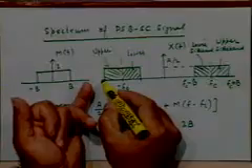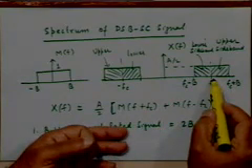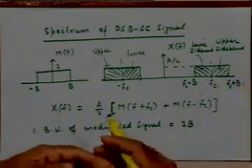No, what we are saying is, certainly we are not getting any additional information. We are transmitting much more information than is necessary to transmit. That is the point. If I were to transmit, let's say, only the upper sideband, that's equivalent to transmitting M(f). If I were to transmit only the lower sideband, that's also equivalent to transmitting M(f). So as far as information content goes, I could have transmitted only one of these two sidebands by removing the other. For example, I could have removed the lower sideband and the spectrum would then look like this. It will have full information because I know there is a symmetry around fc, and I could have exploited that symmetry at the receiver.